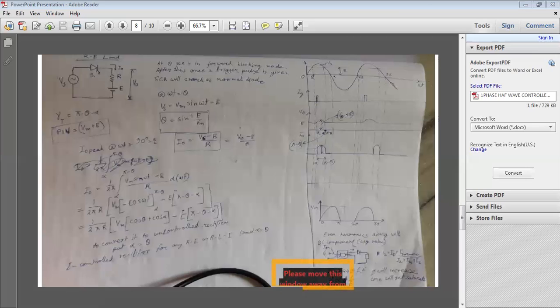With that high power using only a DC component, the transformer will be burnt. So at the source side, DC component and even harmonics should be zero. So we have to remove the even harmonics, and for that we will use the full wave rectifier or full wave converter.